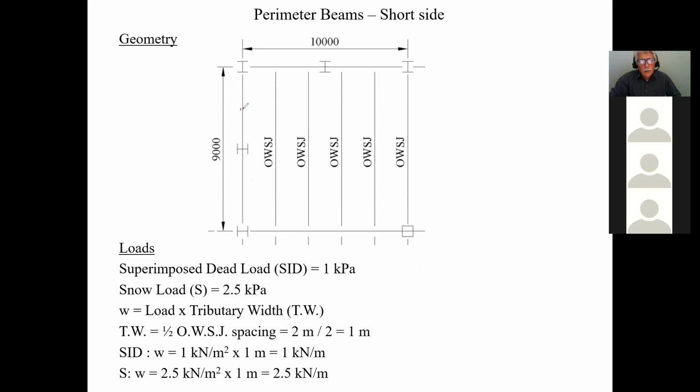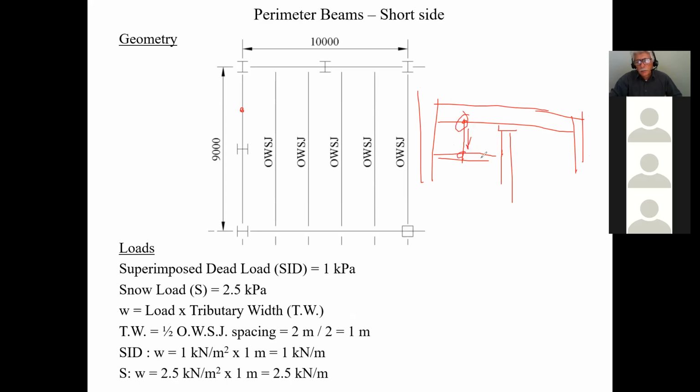You follow? So in other words, here's the beam that you're designing. Here's a column, here's a column, here's a column, here's a column, here's the wind column in between, right? And here's one of the girts. I won't draw both of them. Basically, you make a hole here at the bottom flange, and you come and you support the girt. So therefore, it becomes a concentrated load on this beam. And then there's the other one, you understand?